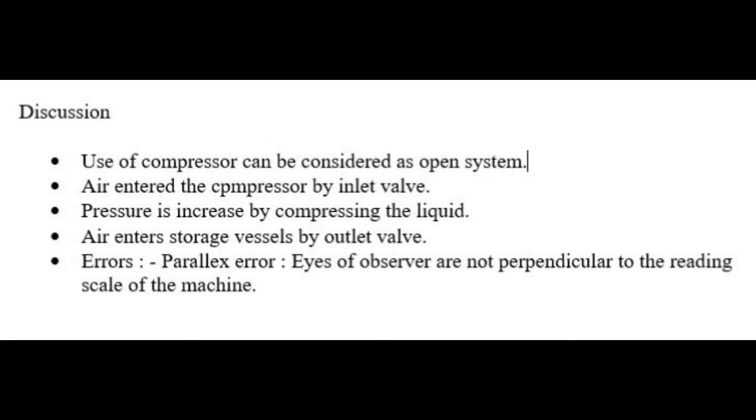Based on the experiment, the air compressor can be considered an open system. Air enters the compressor by the inlet valve. Next, the pressure is increased by compressing the air, and finally, air enters the storage vessel by the outlet valve.